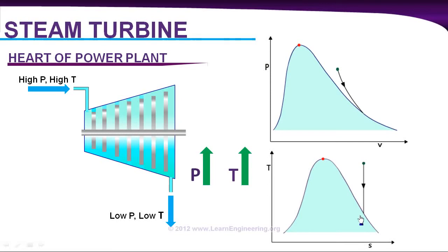Instead, if you can convert this fluid into liquid state, then the compression will require very little energy, or it's easier to compress. So before increasing the pressure, we'll convert this steam into liquid state. For that, you have to reject some heat to the surroundings.